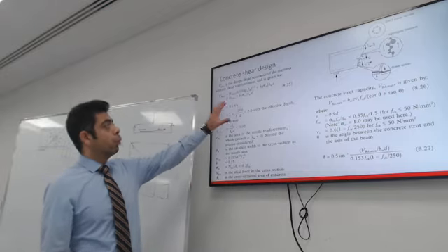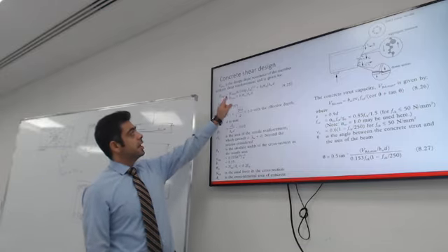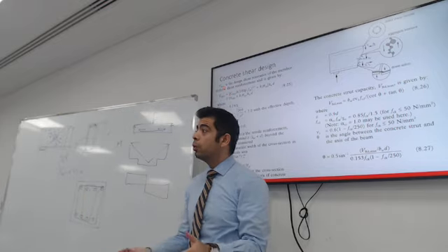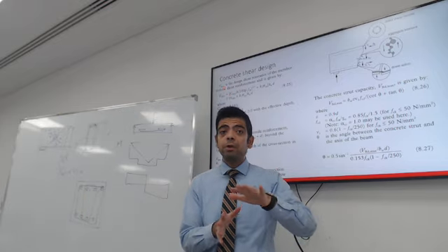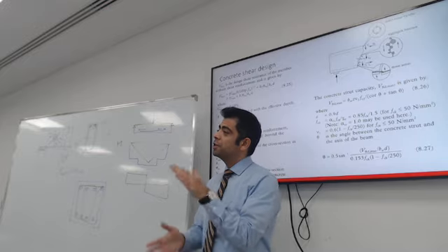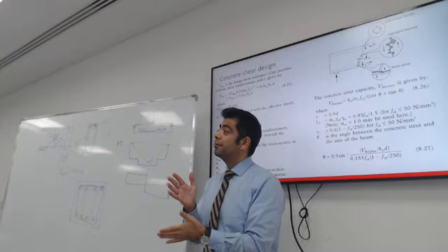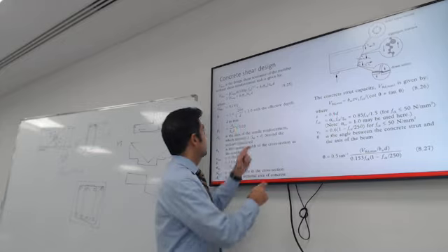So what this is basically explaining is the design of shear with no stirrups, because concrete on its own can resist some shear. So how do we figure out the shear capacity for concrete only? It's this equation over there.